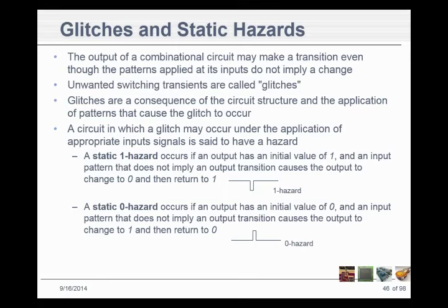This logic analyzer would be right there to tell you. So you could look at your instructions and see how they're being executed, or you could go out and look at the address bus or the data bus or the control bus and see what lines were going high and low. Absolutely fantastic machines for digital troubleshooting.